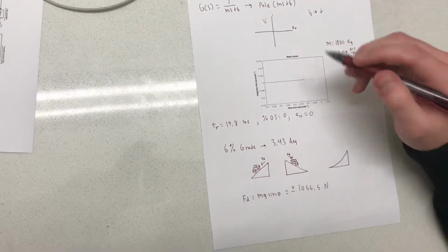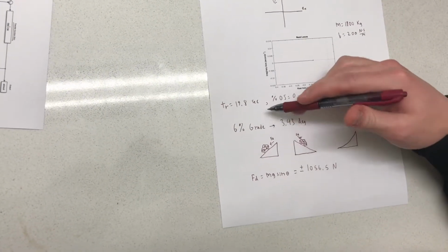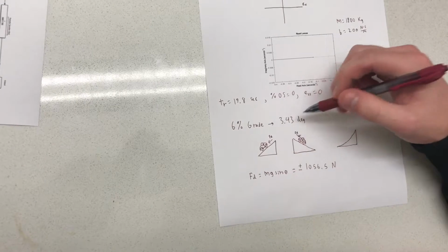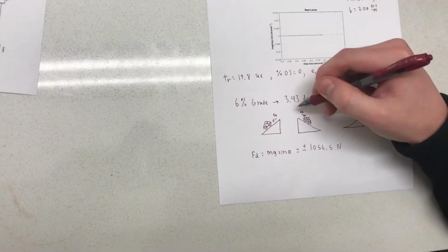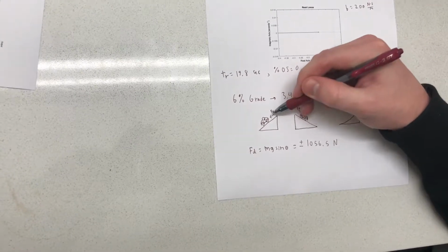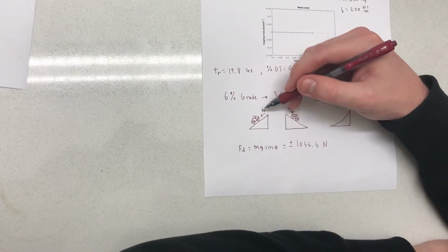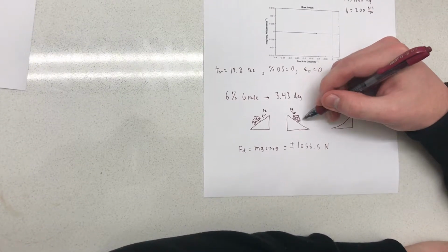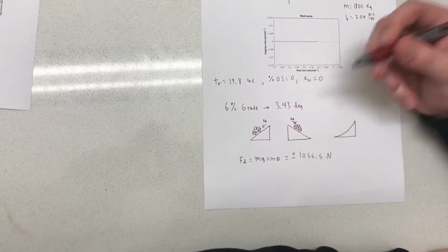Now, the typical disturbance that we're going to face in the US, the typical maximum road grade is 6%, which translates to about 3.43 degrees. So we can see here that when we're going up a road, with our car moving this direction, if it's sloped, we're going to have a disturbance force opposing the direction of our movement. And if we're going down a hill with the car moving this way, we're going to have a disturbance force in the direction of our movement.